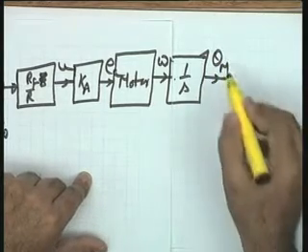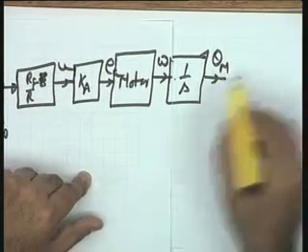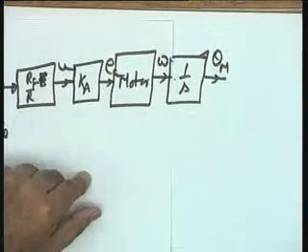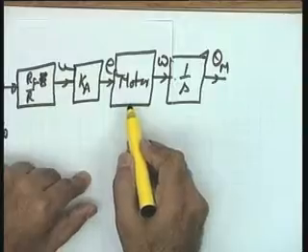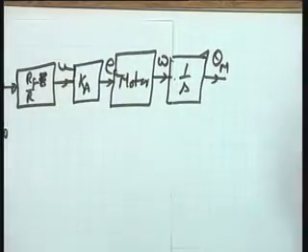Okay. This position theta m from this particular point, now I think you can connect the block diagram, you can convert it to theta L, take a suitable feedback loop through the output potentiometer and the inherent loop on the back EMF also will come. I leave this as an exercise for you to complete the block diagram for the system.